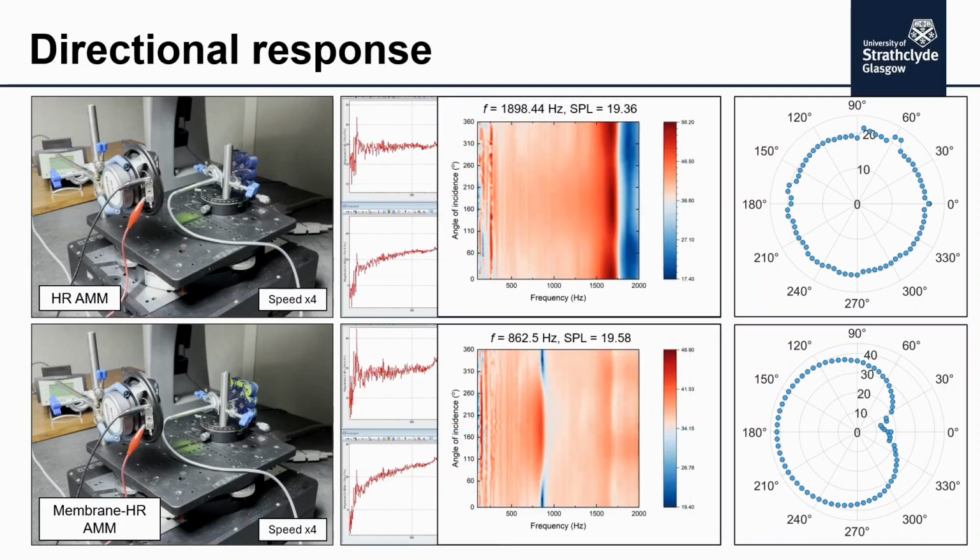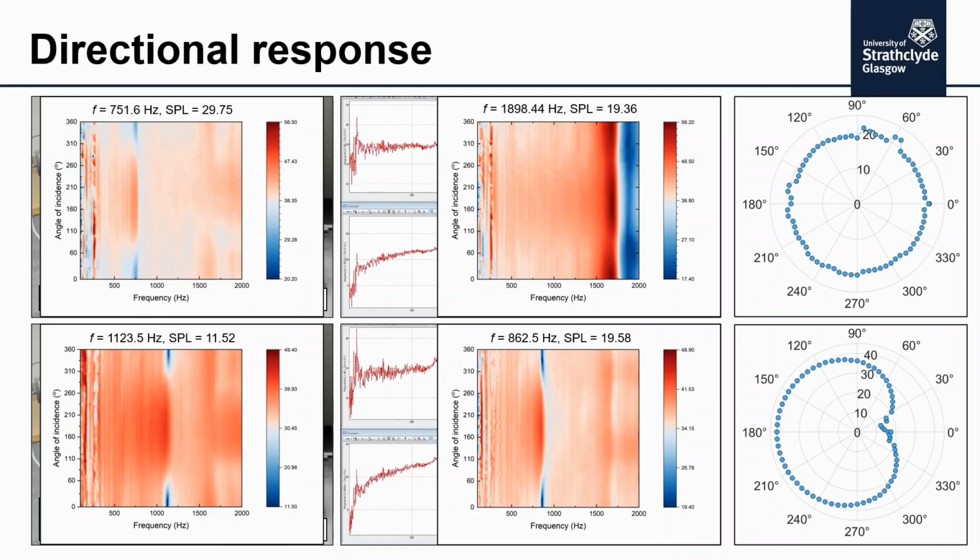If we look at all the frequencies, we see that we maintain that omnidirectional response for the Helmholtz resonator, and we find that cardioid response here, where the bandwidth of the bandgap is given by the width of the blue region. And as I said before, maybe you're noticing that this frequency is not 600 hertz, that's a different tension. As I say, if we change the tension on the membrane, we get different bandgap characteristics.